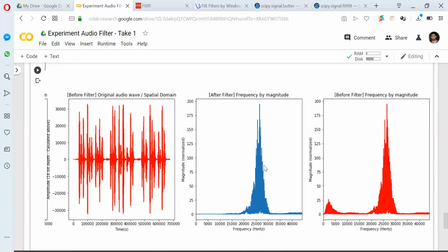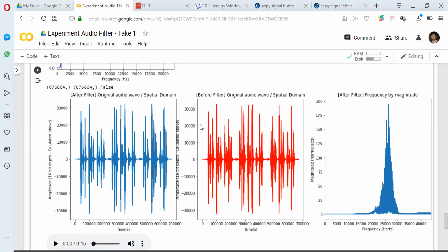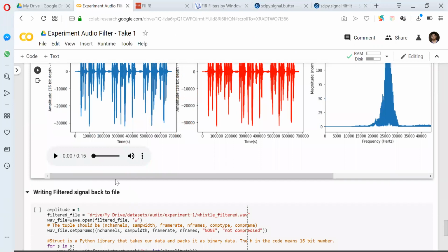If we operate on frequency domain data, that means we have almost the same effect on time series data as well, because these are replicas of each other. If we take the inverse Fourier transform of this data, in the original data you can see a bulky kind of signal, but here it's not that crisp. Let me show you, this is a bulky line, whereas this is not a bulky line. On operating this, does it clip out the noise? Let's see.